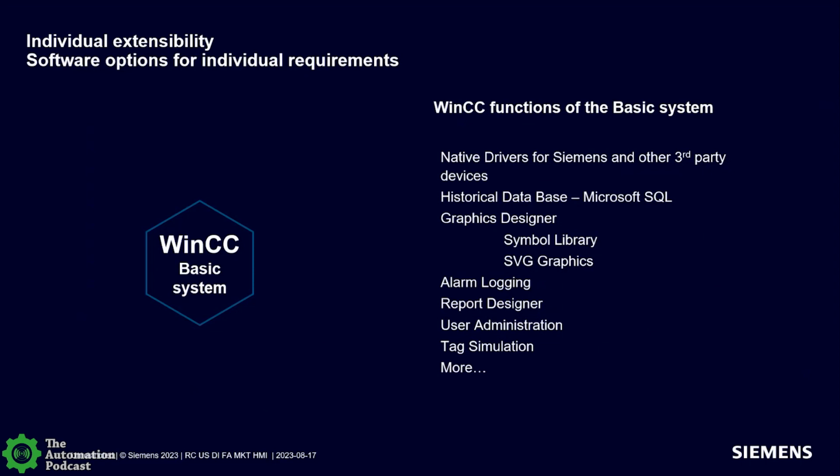We've recently, in the last 4 or 5 years, converted all our graphics to scalable vector graphics, which allows you flexibility. So when you start scaling pictures or zooming in, zooming out, it keeps you the nice clear pictures. But you can also take objects and break them apart and start modifying the internals based on tag count. An example I always show is a boiler that's an SVG graphic, and I can say take the tubes in that and change the color of the tubes based on the temperature of the boiler water. For the flame, I can show the flame length, and all this other stuff. So you can actually get graphics that represent what's going on out in the field.